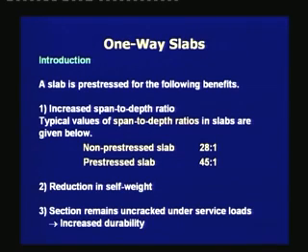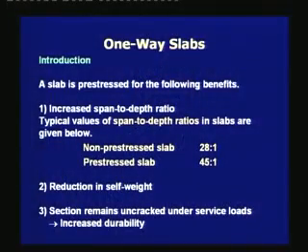That means here you can see that a prestressed slab can have a larger span compared to its depth, and this is a big benefit when we are looking for large column free space. Thus, one very important aspect of prestressing a slab is to increase the span to depth ratio. The second benefit is the reduction in self-weight.